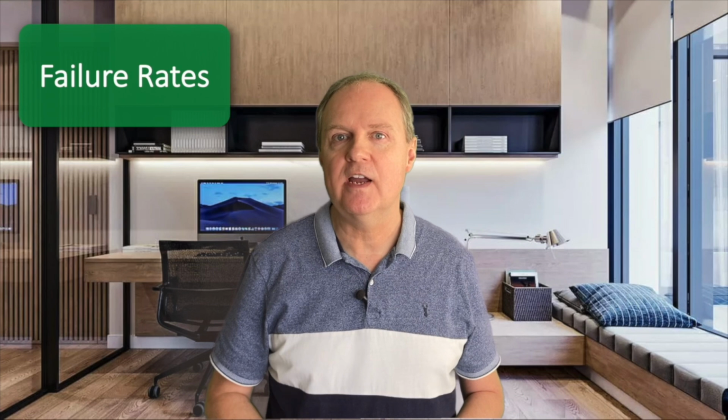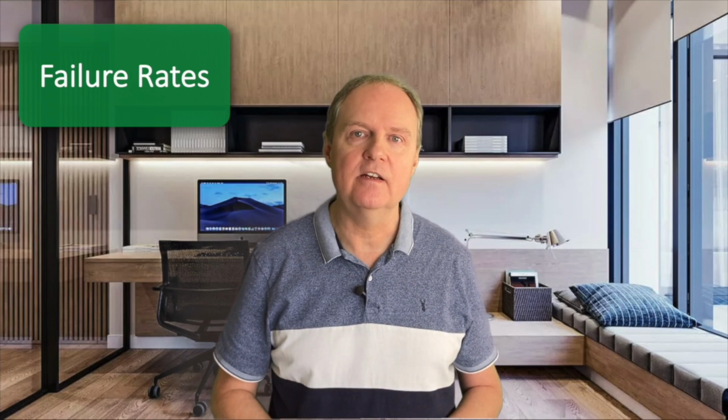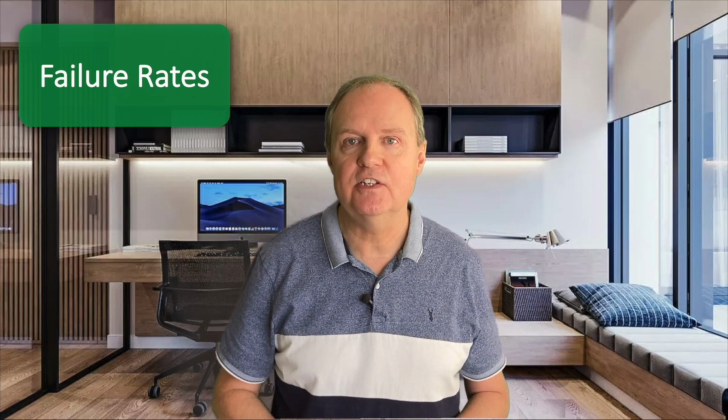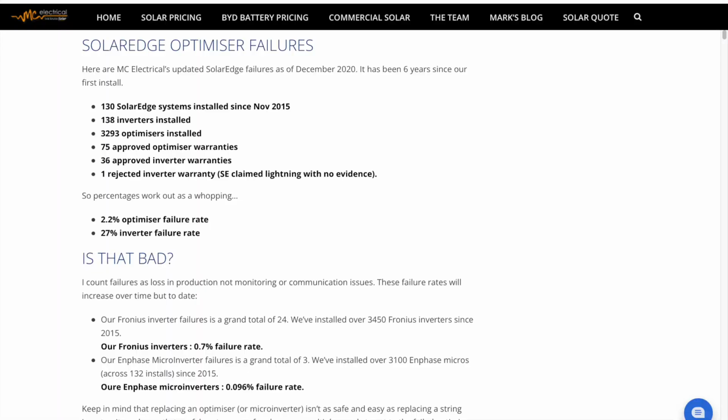Remember I mentioned Mark Kavanagh from MC Electrical earlier? Well, after many hundreds of optimizer and microinverter installations, he has amassed a powerful set of statistics on the failure rates of both. Here is a blog post Mark published in 2018 but updated in 2020. I have to say, it doesn't look good for SolarEdge optimizers. The failure rate after nearly 3,300 unit installations over 5 years was over 2%.